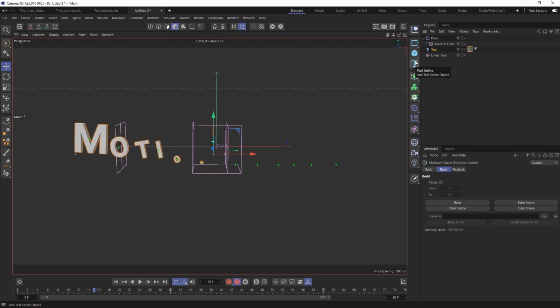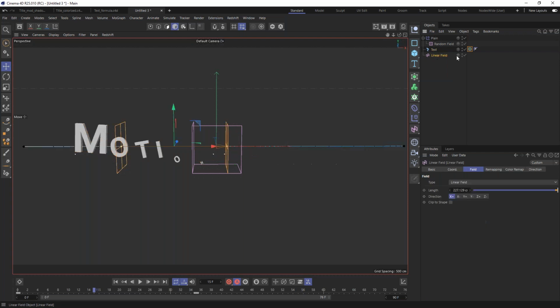Okay, so this is one way to animate. I like it. It works pretty well, but the problem, if you want to use it as a preset with someone who doesn't know Cinema 4D very well, is that you have to know to adjust your linear field and so on. So there's another way to animate. There is one I really like, using the inheritance effector, so we're going to see that. And after that, I'll show you how to do the 2D and a half stuff.